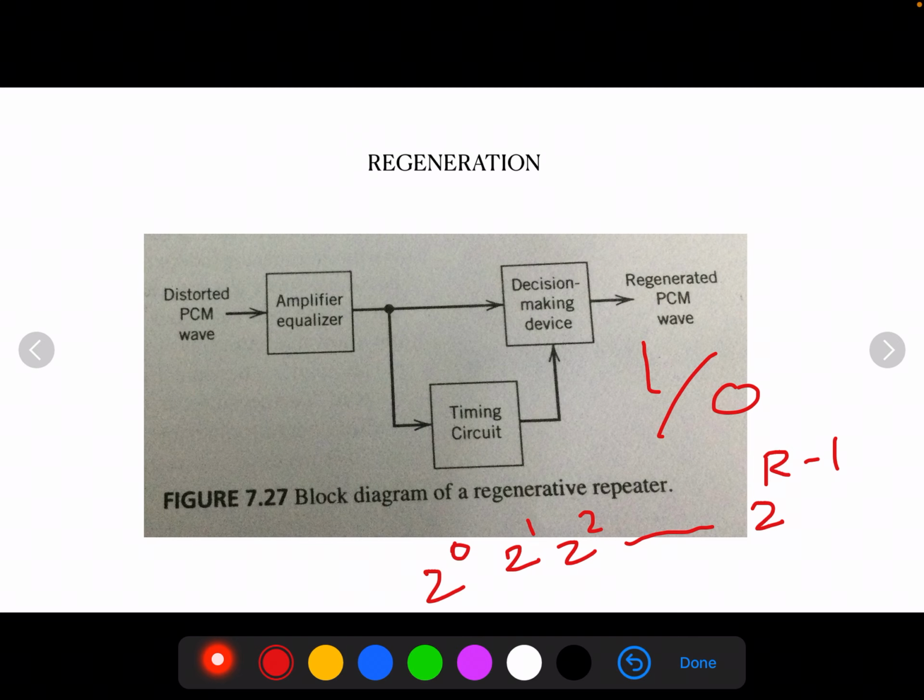The last topic is multiplexing. In applications using PCM, it is natural to multiplex different message sources by time division, whereby each source keeps its individuality throughout the journey from the transmitter to the receiver. So, this individuality accounts for the comparative ease with which message sources may be dropped or reinserted in a time division multiplex system.